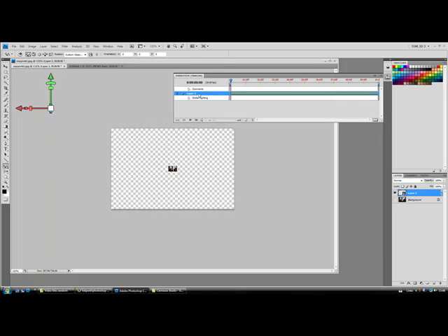Okay, now let's open our timeline. Let's turn down the squirrely and put a keyframe on the 3D object position. We don't want to use a normal position, we want to use the 3D object position. So we'll click there and set that keyframe. Now I'm going to move the time indicator controller to 3 seconds, and I'm also going to bring down my work area to 4 seconds. So we're going to have 3 seconds of animation and 1 second where there's no animation.